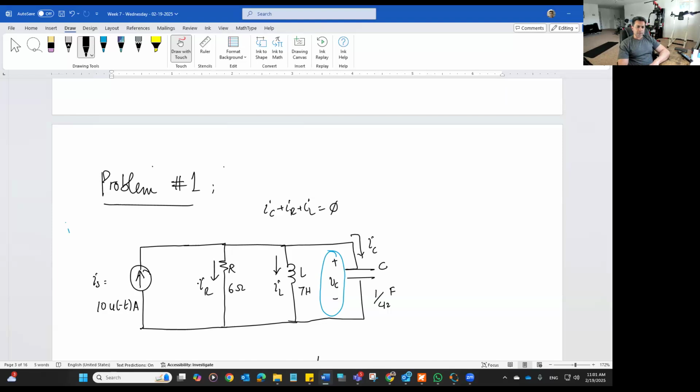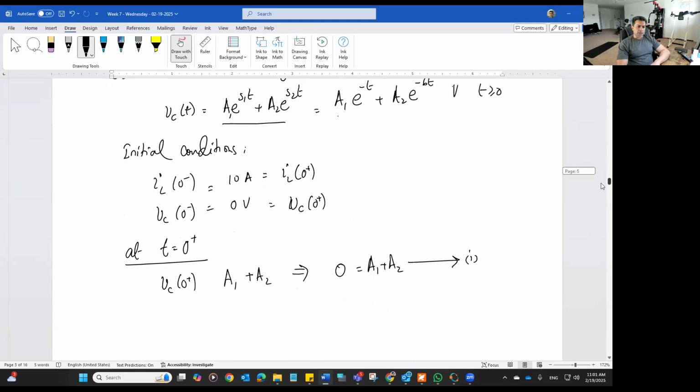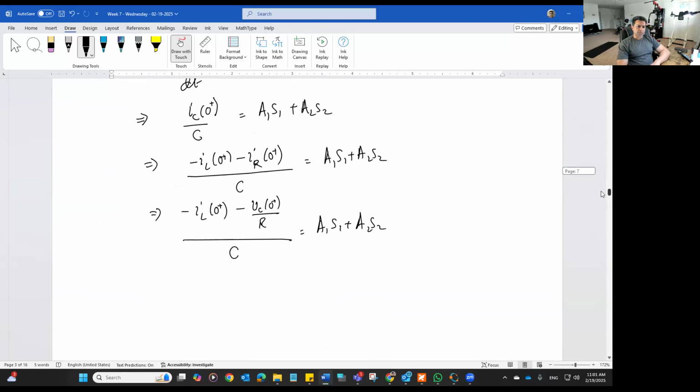So this current is 0, the capacitor will still be acting as an open circuit, because capacitor voltage cannot change instantaneously, and the voltage across the capacitor will still be 0. So all the current passing through R, L and C will still be going through the inductor, because again, inductor current cannot change instantaneously, and capacitor voltage cannot change instantaneously.